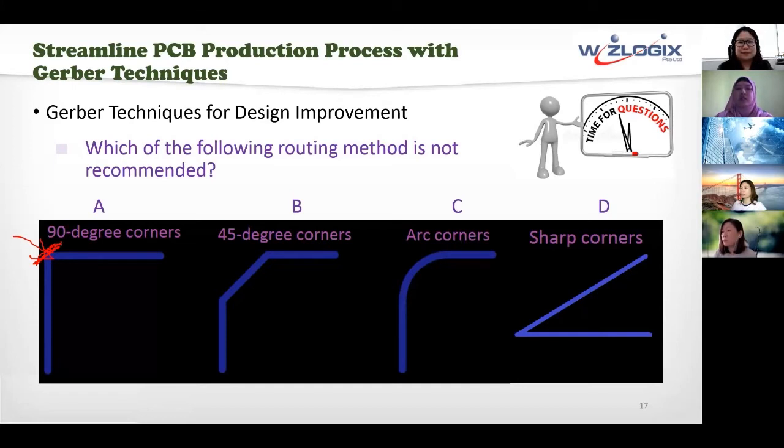So this is not a very good chemical removal stage if you end up with over etching at the corner here. As well, on this inner corner here, you can end up with an under etch, whereby too little copper is removed. So you end up with something like this. Although you get the same trace width as the one on this axis or this axis, because it deviates from your actual design, it's not a good practice.